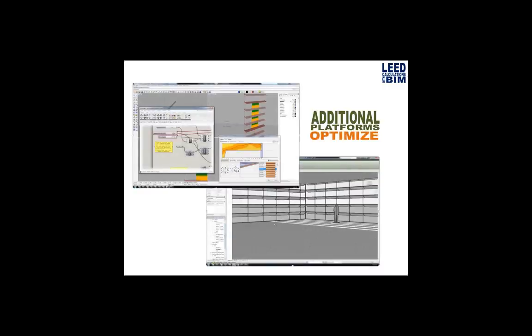So there are a few different tools that you can look at. So you can look at multiple options in order to optimize your design. Here we're using Rhino with the Grasshopper plugin to analyze some of the best locations and dimensions for exterior shading devices. And then we're also using Galapagos, which is an evolutionary solver, which uses a genetic algorithm to then help give you the optimal results for the design, based on your project's location and orientation.